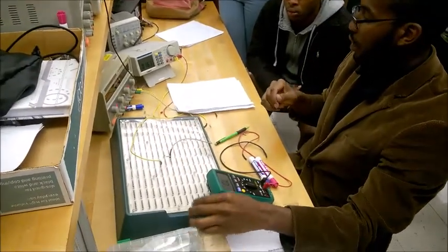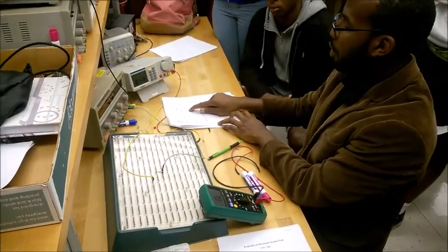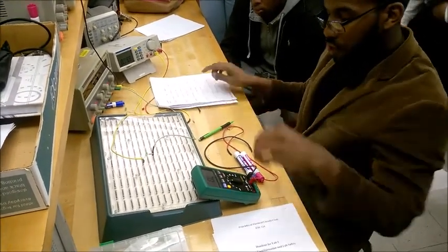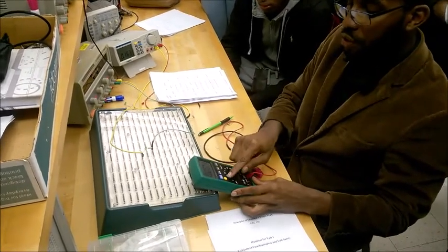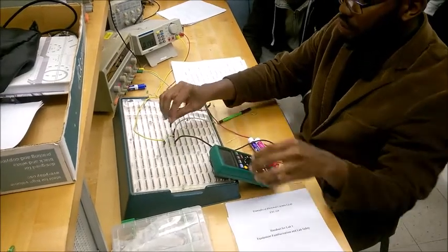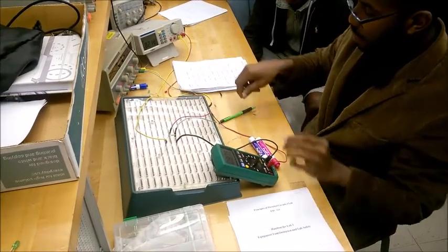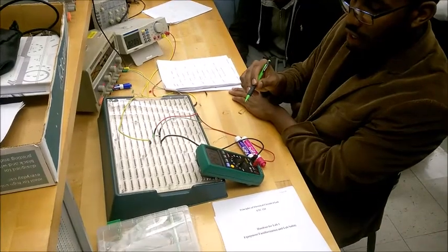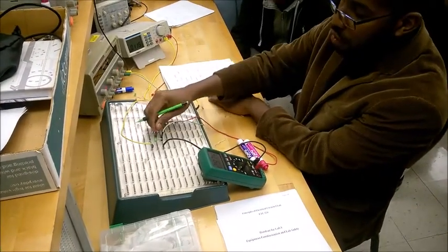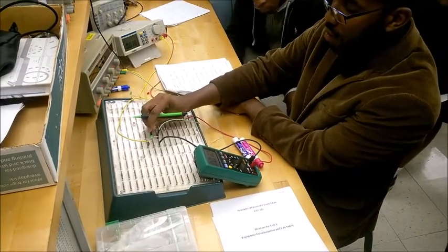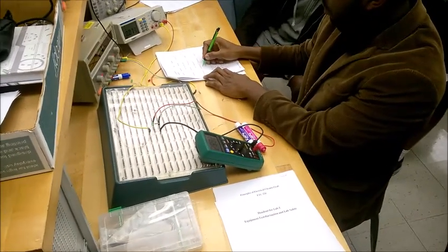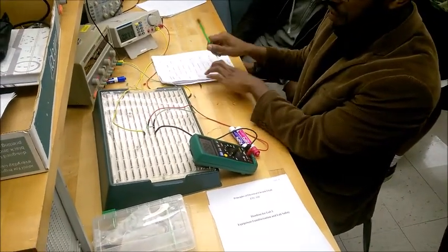Alright? Okay, next step the lab says is we should measure the power supply voltage, and then we're going to measure the voltage across the LED and the voltage across the resistor. These are very easy. I go to DC volts here, and I want to measure the voltage across the resistor. So I put this across the resistor here, and I take the voltage: 2.971 across the resistor, and I do 3 such measurements. Okay, this one is going to be 2.990. At the end, we're going to get the average of these 3 readings.